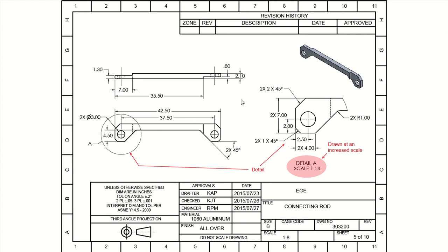Okay, so where is the detail? Now we're drawing this first. We look at it from the top view, and then we have our front view right there. So we're going to take this section out, so we'll remove it, bang. That is the section that we want to detail because you can't put all of your dimensions in there, full dimension, because of the small part or feature right there. So we're going to cut this feature out. So bang, you get a real big detail view of that part for this section.